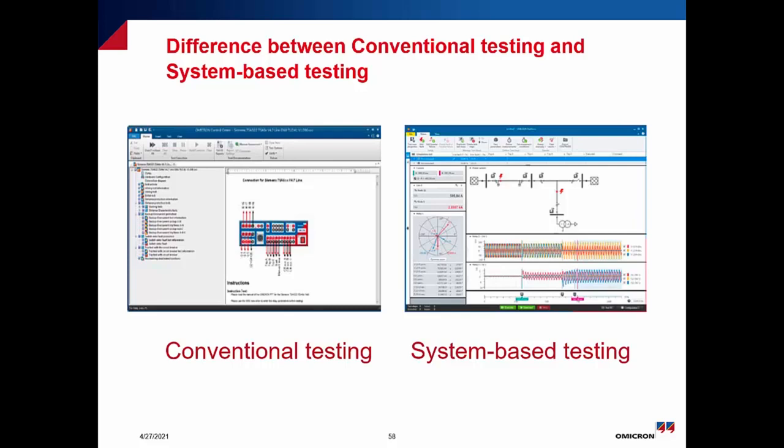What kind of important information do we need to apply, we need to check? Let me give an example. As you remember in earlier slides, I showed that CT saturation or CT transient behavior is very, very important and very essential to be considered during testing transformer differential or differential in general. This is a very important point we have to consider. What else? We can also say that restricted earth fault can be done by system-based testing easily by controlling multiple CMCs with only one software. It means that I can test differential for a tertiary, 3-winding, at the same time. Yes, this is what we will do right now after the theoretical part.